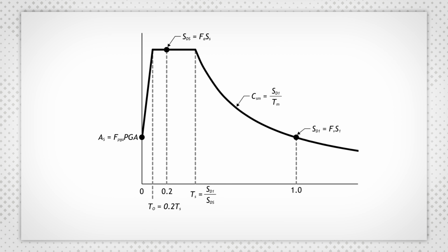The acceleration a bridge experiences is a function of its period of vibration. If we plot period along the x-axis and acceleration response on the vertical, we see that for short periods, seismic accelerations are very high and drop as the period increases. Stiff bridges, of which there are many in the world, fall in the highest acceleration portion of the curve.